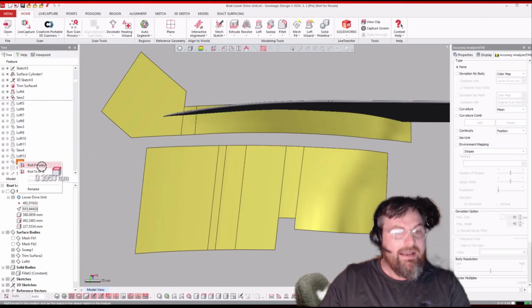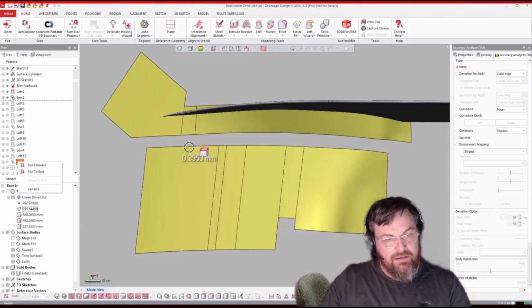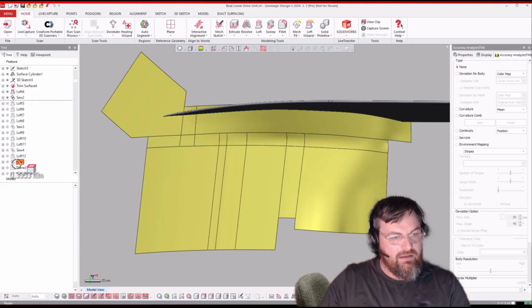So some people might ask, why don't you just select here and there and make it all fit together in one shot? What ends up happening sometimes when you have different ordered paired sides is that there's some wrinkling of the NURB surface if you don't map this to that, and make it very specific. Here, I accidentally did not hit move forward. So you see here, what we're able to do is go ahead and map these so it's a nice order.